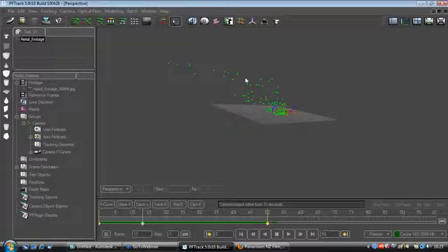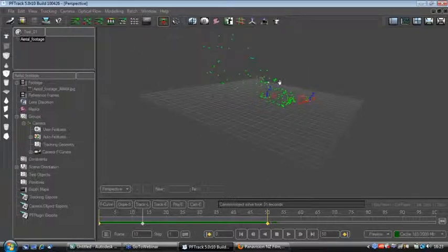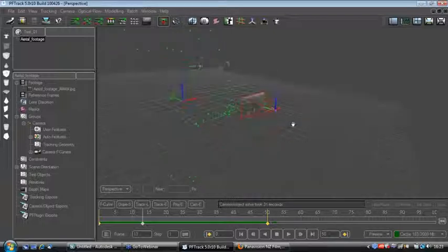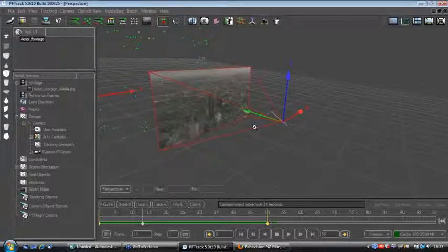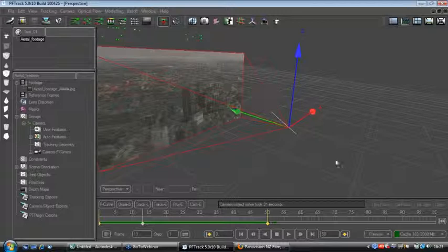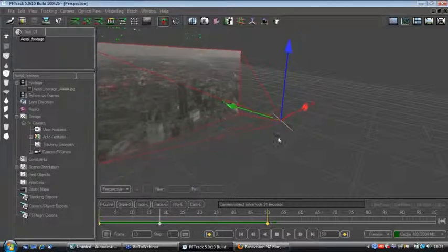Now to orientate and navigate this 3D space, it's the same as navigating a 2D space. We go to the navigation icon and then use left mouse to tumble around, right mouse to pan, and middle mouse to zoom in. Now I can just about see our camera. And the actual camera translation through the scene looks to be good.